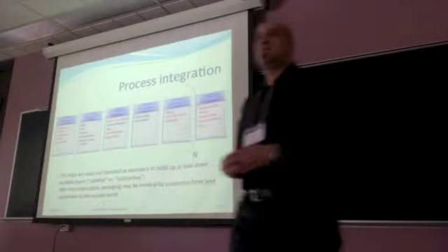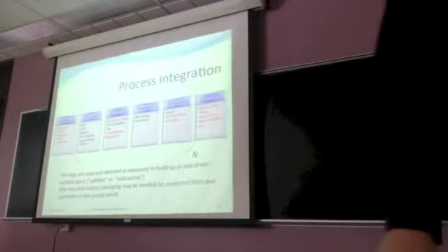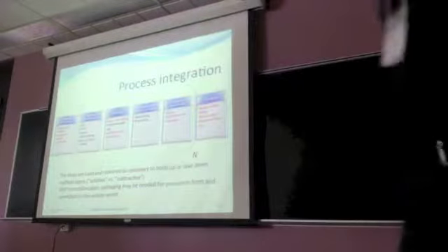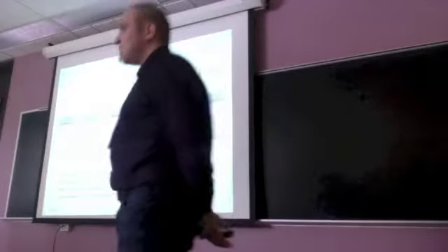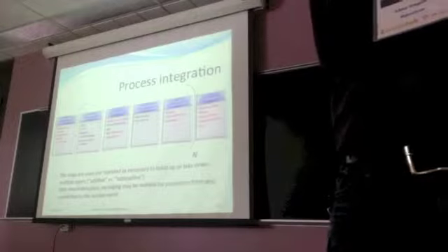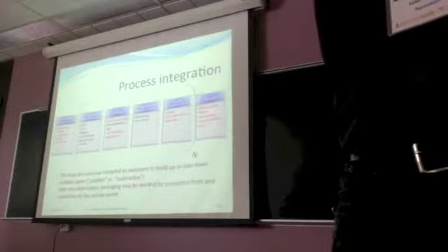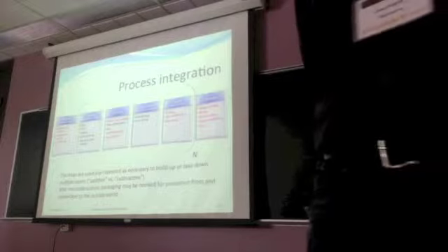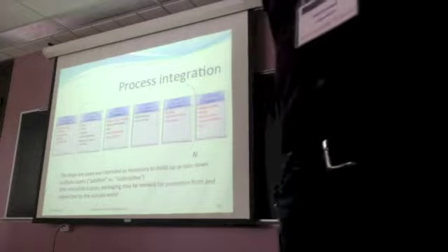Yes? In Tal's case, there are many different substances being put on, right? Sorry, can you repeat? There are many different substances being layered. Yeah. But can you layer multiple substances using all of these approaches? For sure, yes. It's very hard to compare the semiconductor industry and a research lab. In the semiconductor industry, you can use all the material you want. For example, metals. You have to be very careful with metal because metal is very poisonous for silicon. You can create defects, and the transistor cannot work properly.